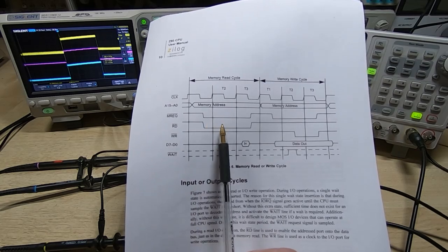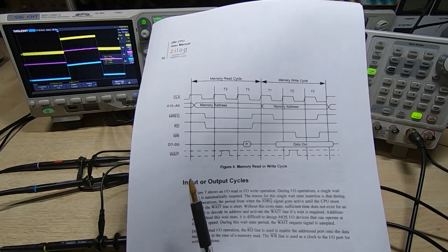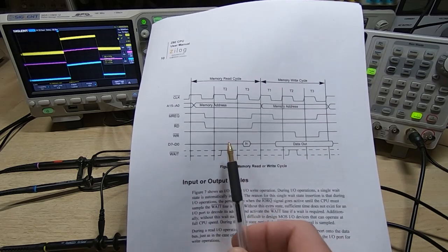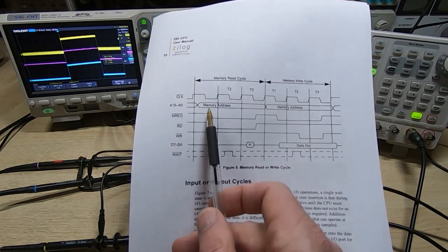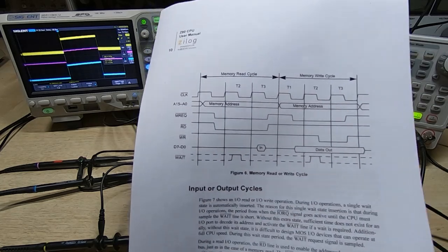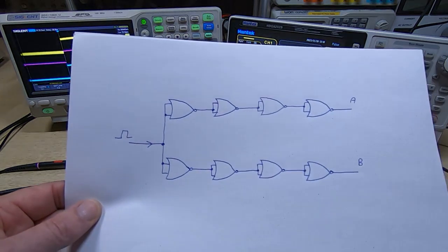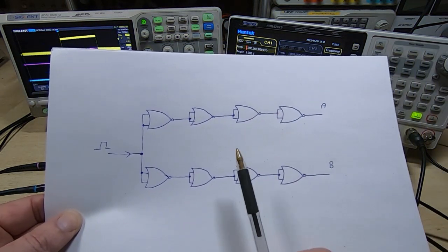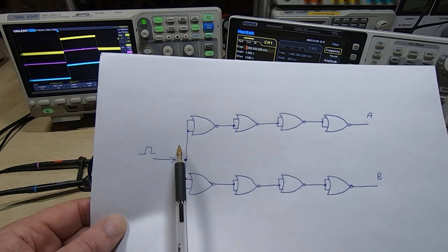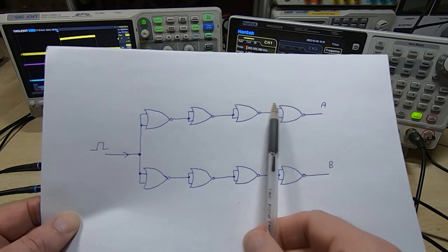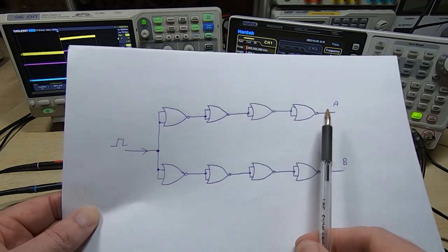So for example, if it's DRAM, you have to carry out quite a few operations to get the DRAM to respond. So from the input, the clock edge going into a circuit, you could have anything from one gate, if you just got a ROM chip connected, for example, up to 6, 8 gates or even more between the signal edge and what you're trying to drive. And that's what these circuits really represent. I've limited it to 4.